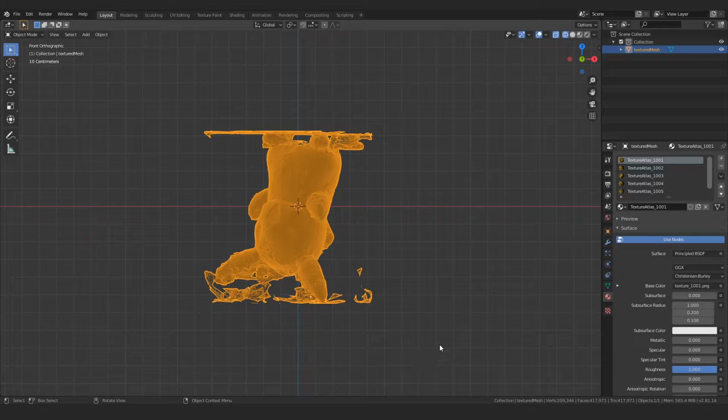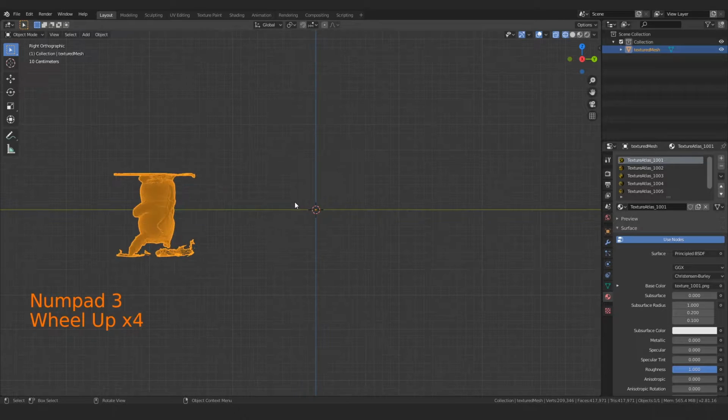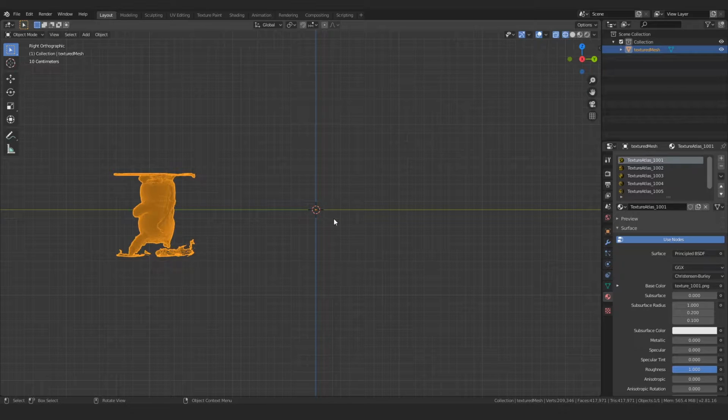We're looking only at the front, and we're omitting the y-axis because it's running directly perpendicular to us, directly into our face essentially, and it's flattened out so you can't really see it. And so you'll notice that the z-axis does show up in this 2D front orthographic view. Then if I use my middle mouse button to tumble out, we move back to a user perspective view. If I press the 3 button on the keyboard, we have right orthographic, which includes the y and the z axes, but no x-axis because that's the one that's perpendicular to us.